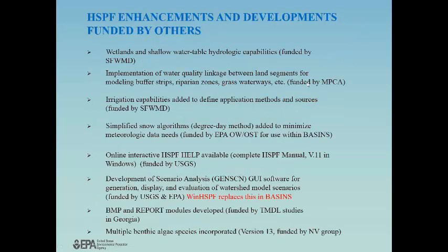Some recent enhancements and developments that have been funded by others. There's a shallow water table condition that allows you to track the actual water table as it moves within the soil profile and all the way up to the surface, funded by South Florida Water Management District. The implementation of water quality linkages between land segments, for modeling buffer strips, riparian zones, and grass waterways, was funded by the Minnesota Pollution Control Agency. Irrigation capabilities are also funded by South Florida Water Management District.